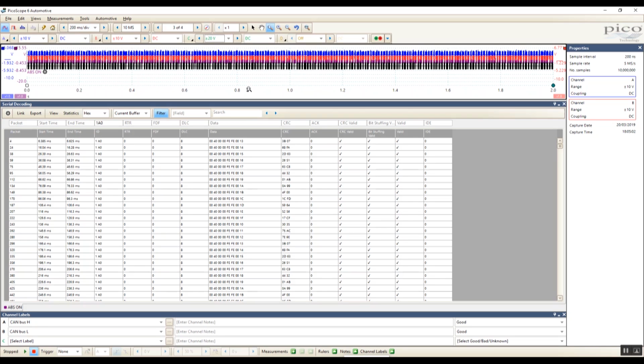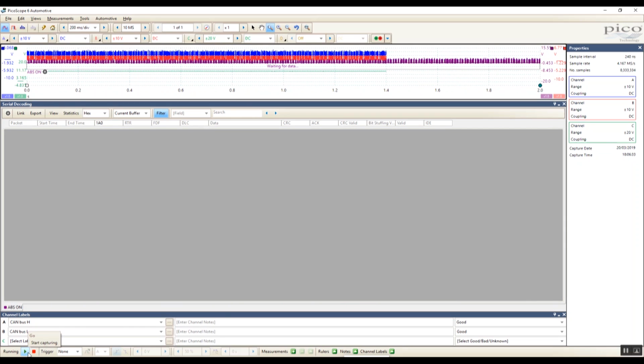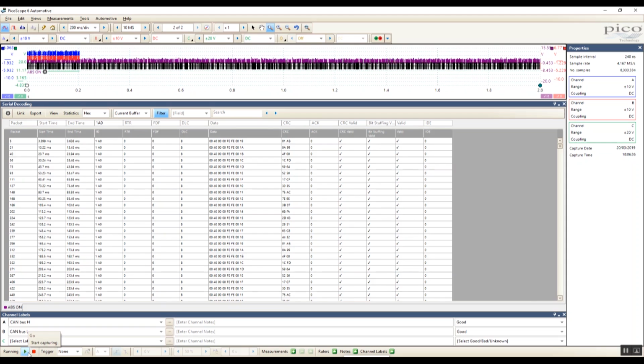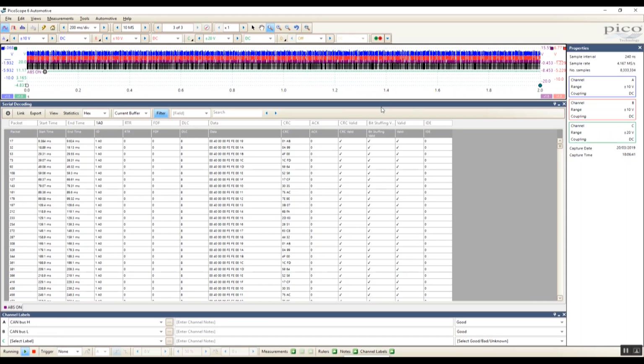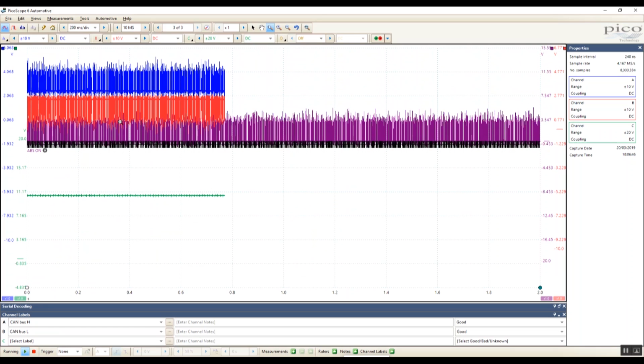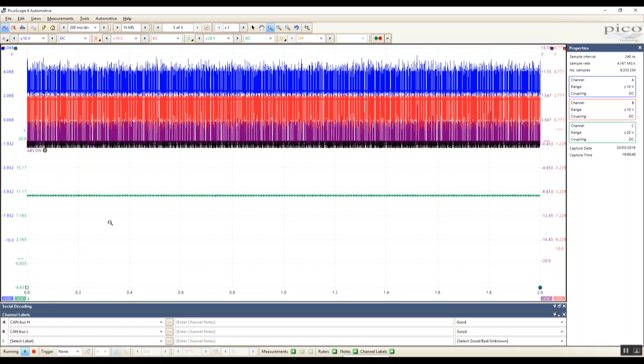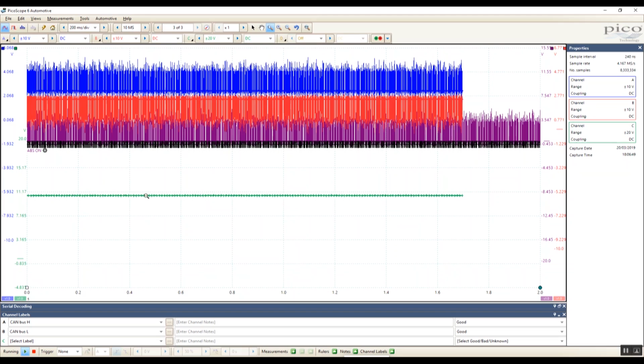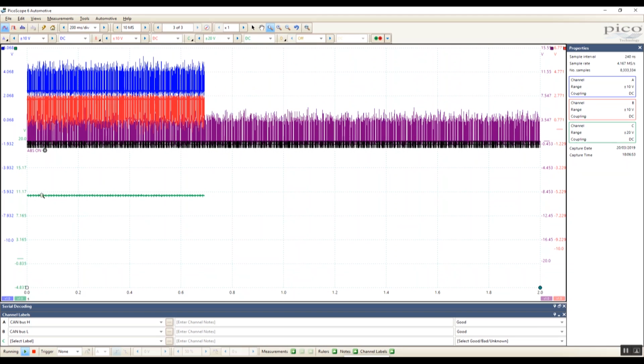And if I were to run this now, so let the buffers fill up, the software now is just looking at ID 1A0. It's collecting other ones as well. If I just minimize this, you'll see far better the raw data. So here's our brake pedal at rest.